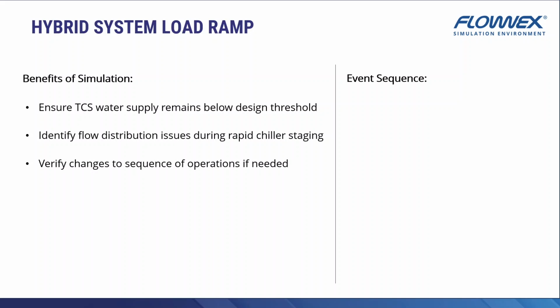Unlike the previous thermal ride-through scenarios, this study focuses on the system's response to rapid changes in IT load, showing how chillers, pumps, and buffer tanks interact to try and maintain stable supply temperatures and prevent temperature excursions. With some minor control updates, the same Flownex network that was used for the thermal ride-through studies can also be used to simulate transient heat load fluctuations in the system.